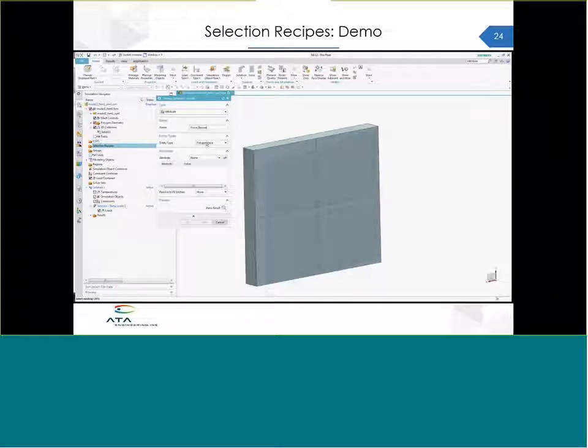We'll change our entity type. We have a bunch of different options, but we'll select polygon face. For attribute, we also have a few different options. As you can see, name, color, and user attribute. We are going to use name. We'll hit add attribute, which is that button there. Then for our name, we'll change this to Force.